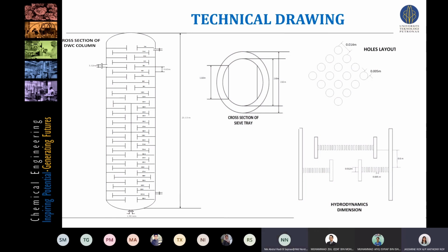Because the top you mentioned is negative 100 something, and the feed is 60 something. Inlet temperature negative 63, yes. Top is negative 123. And bottom is negative 73. Your temperature profile looks strange. How many stages is this one?